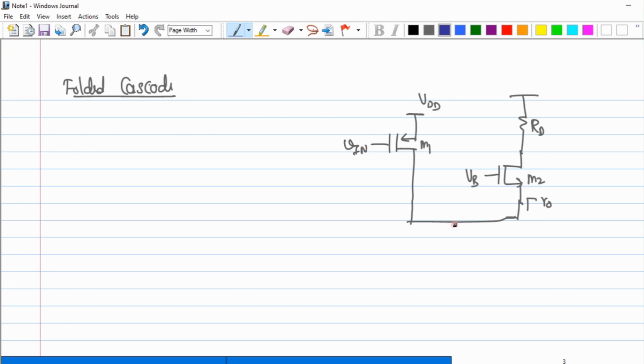Okay, I will not make you think too much. I'll just put a tail current. Now, I have IS, and the value of this IS comes from two transistors, right? The DC current that flows here is basically a summation of the current that flows through M1 and the current that flows through M2, because there is a potential difference from VDD to ground. Again, there is a potential difference from this VDD towards ground. So I have current in both the parts, and they both add up to create this IS. Is that clear? Now this circuit is properly biased just because the currents are flowing. Clear?